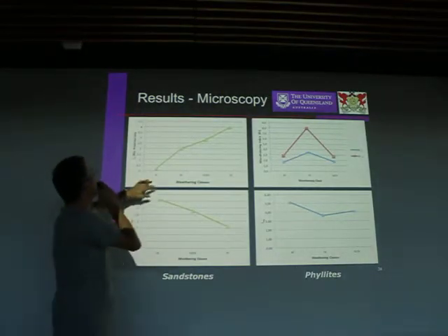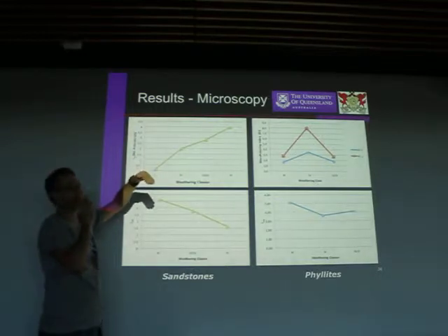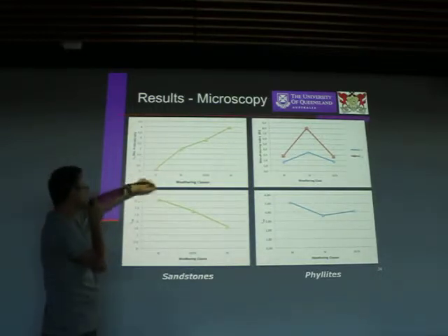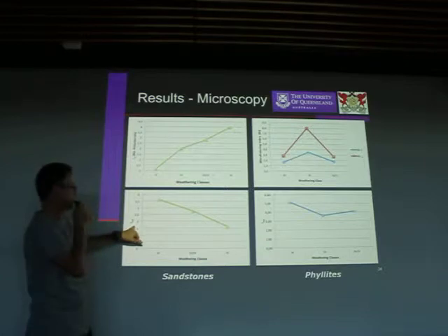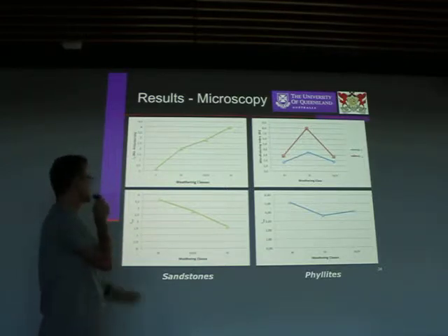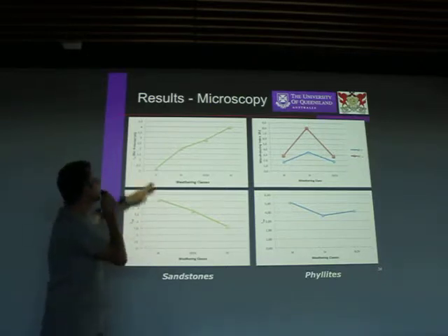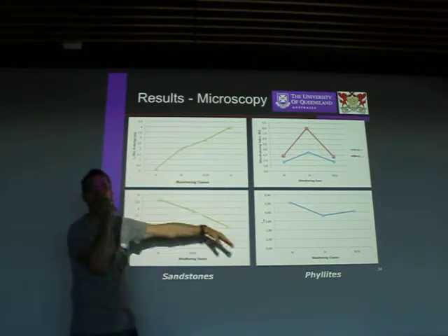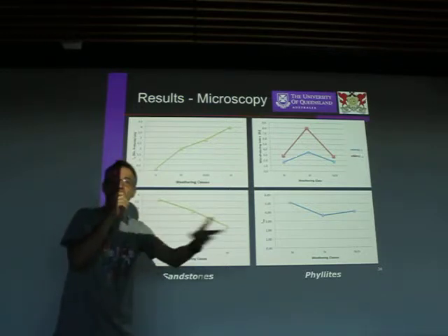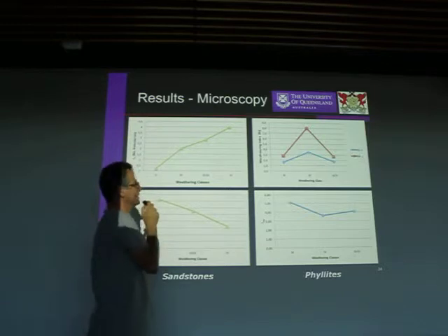And here we have some results from the microscopic indexes. Here's the microfracturing and the IMP, that's the micropetrographic index, the sound to weathered material ratio. And you can see that there is a very strong trend with the weathering increase.